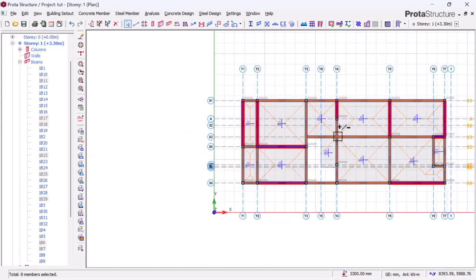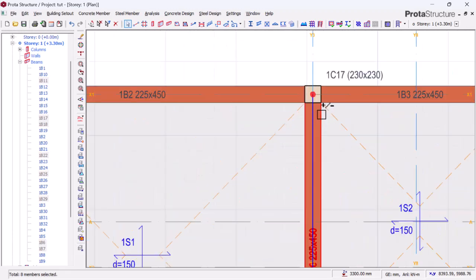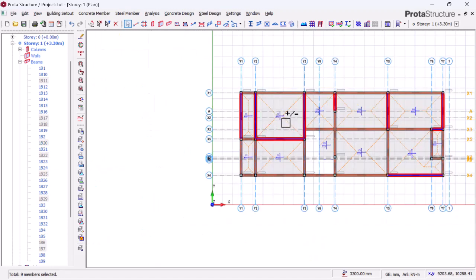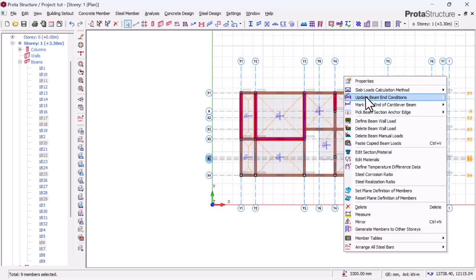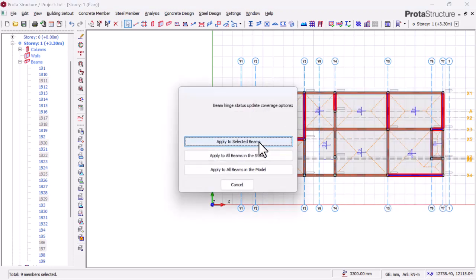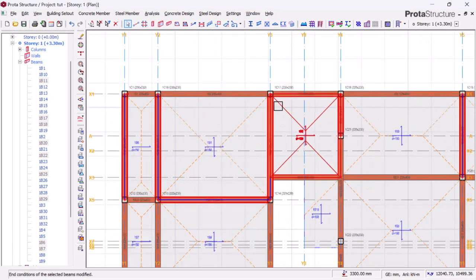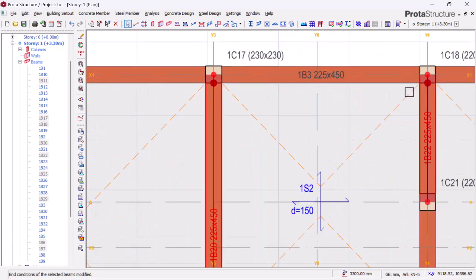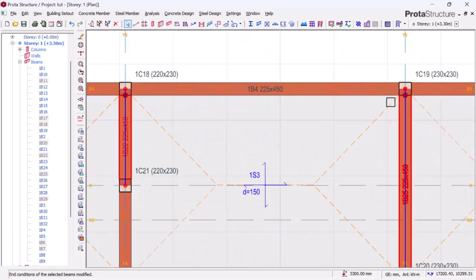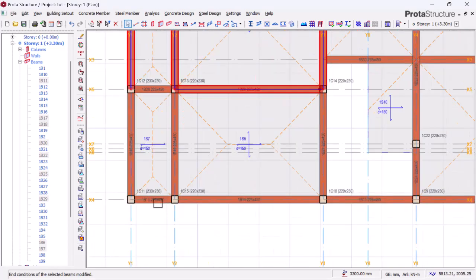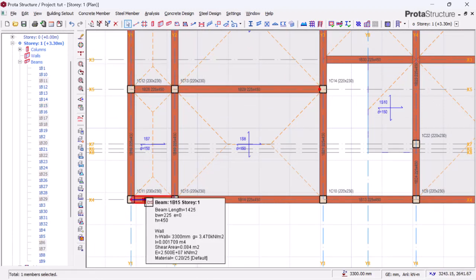Since we are done highlighting all the J members, we have another one here. In doing this, you remove your hand from the shift, you right click, and you go to update beam end, and you click on J, apply to selected, and it's going to automatically fix all the J without you doing it one after the other. A similar thing will go on the I.